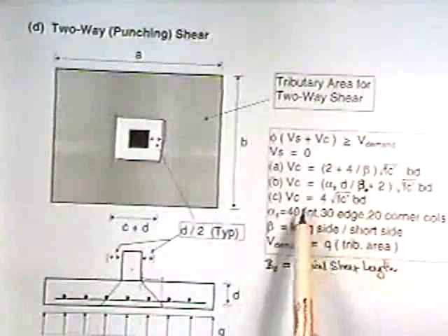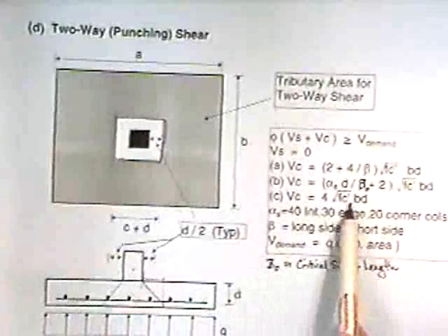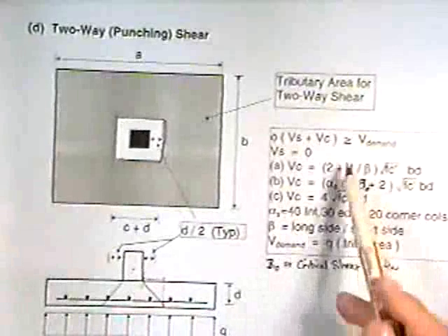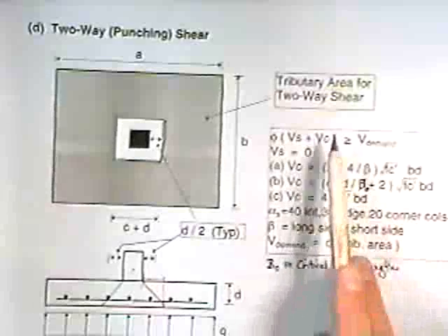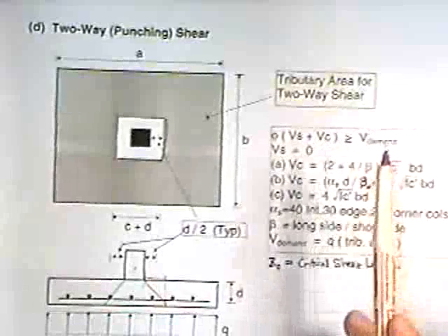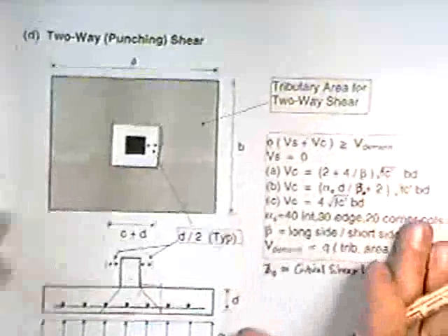The third condition is that the resistance in the concrete is 4 root f'c times b0 times d. So you figure out which one's the smallest, and you go with that. You make sure that your capacity now exceeds the demand, and then it's okay for two-way shear. You also have to check...